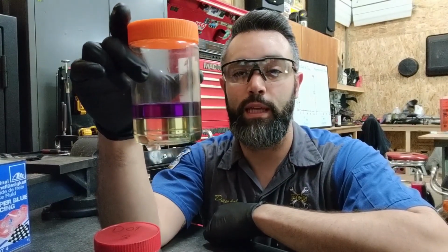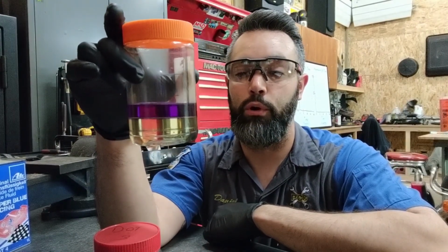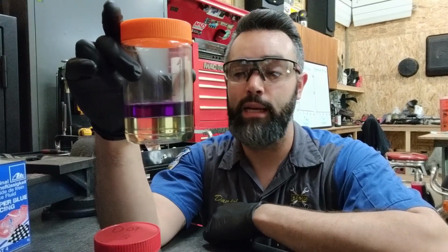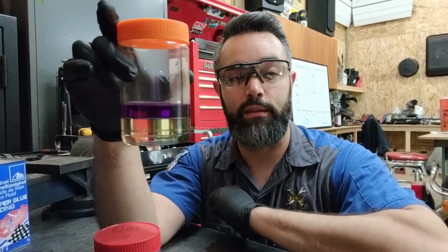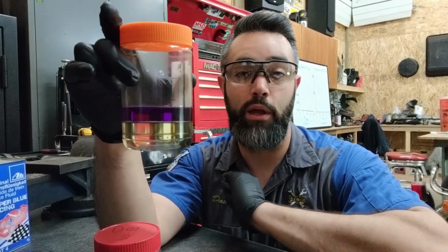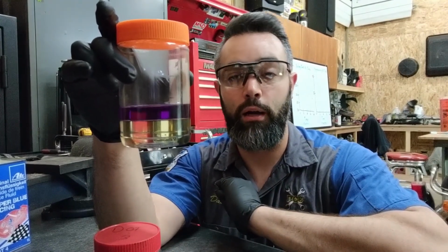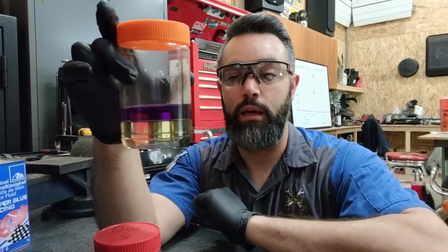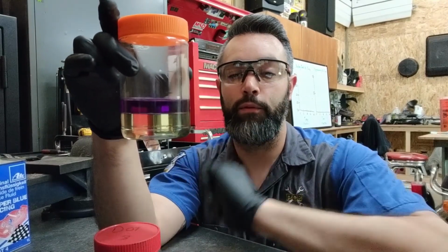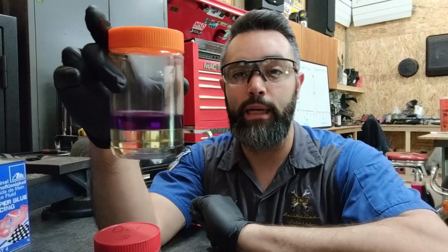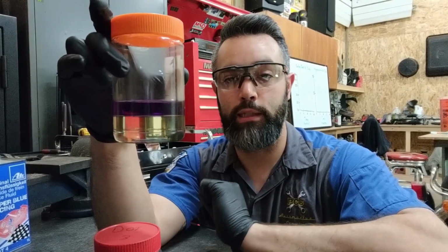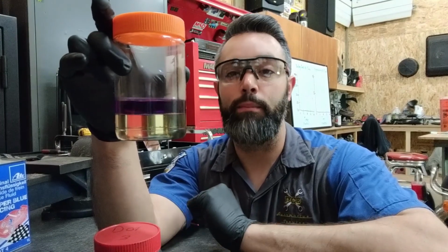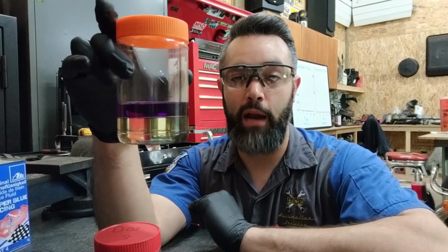The seals for these systems are designed to work with the fluid that is specified. So if the system is using DOT 5, the seals and the O-rings in the systems are compatible with silicone. If it is specified for use with DOT 4 or DOT 3, they are glycol based systems, and the seals and the O-rings in the system are made to be compatible with that fluid.